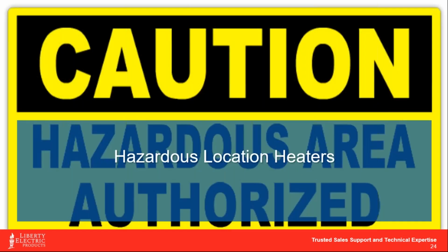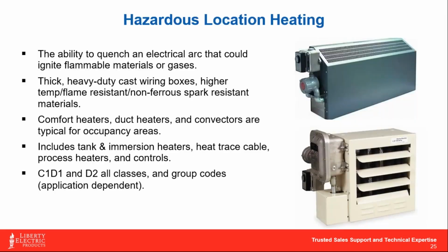Okay, so hazardous location heaters. We did touch on this a little bit with air heaters. The big gist of a hazardous location heater is the ability to quench spark at the point where we bring power to the unit. These heaters are designed with non-ferrous materials so that we're not promoting anything that can create a spark, because hazardous location heaters are typically used in areas where you've got combustibles.